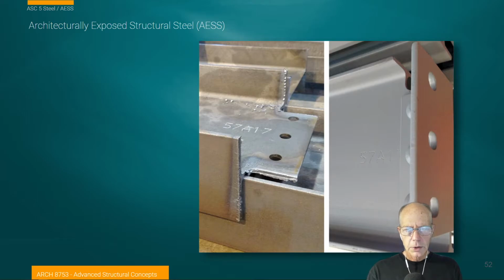Once again, as I discussed, the way this section is cut is we have 3 bolt holes to transfer the shear load to what will probably be the column. But we have the flanges, the bottom and top flanges, cut well back of its intersection with the column. That's so that this beam doesn't transfer the moment, the twisting forces of its deflection, to the vertical column. With that, the fabricator flame cut these using a torch, probably on a CNC torch machine that precisely cut these shapes out. And when it does that, there is this kind of spatter of the molten metal.